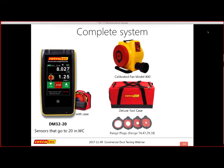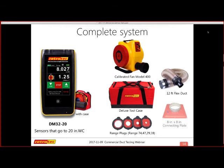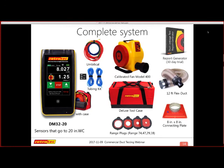The ones that you have now can go up to around 5. The newer ones may do 10. But in general, the residential one will not work on a commercial fan. So you cannot just get a fan and use your residential gauge. As well, we're not really fond of you using the 20-inch gauge on a residential system because it just isn't focused and calibrated for the range of results that you're trying to get. So in general, this gauge, the DM32 20-inch, is designed for the commercial systems that Retrotech sells. But you get a variety of ranges, so you don't have to buy them individually.